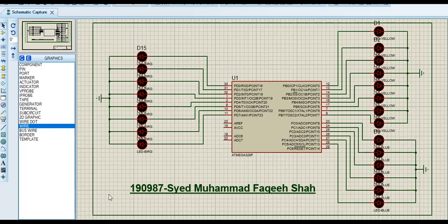Those are 35 in hexadecimal, and F, that is 4 zeros and 4 ones being added, and these added values are displayed on port B. Port C shows us the OR function of 0x04 or 0x68, and the value is shown on port C. On port D we have the value of 0x54 XOR 0x78.